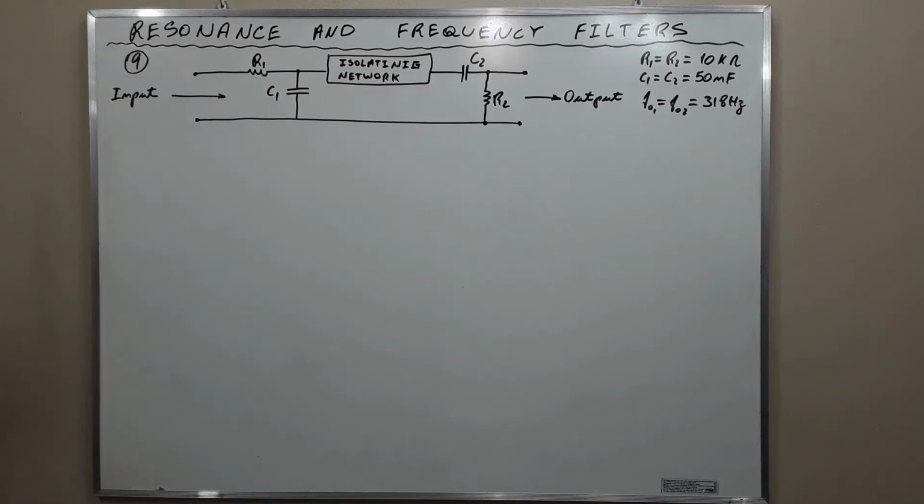The solution: as capacitors behave as short circuits to high frequencies, the shunt connected capacitor C1 will drain to ground the high frequencies.